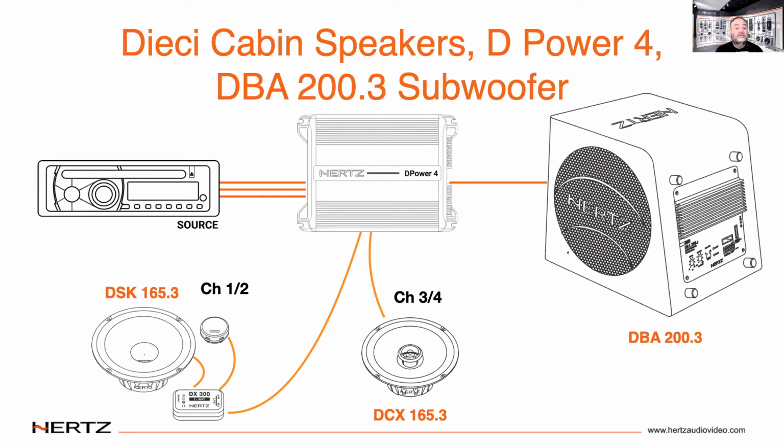Now, also, there's a high-pass crossover filter in the D-Power 4 amplifier. And if you use that, you can attenuate the low bass notes before the cabin speakers try to play them. So that would lower the distortion even more from the cabin speakers and improve the dynamics of the entire system. And it has some other benefits, which we'll explain more in a moment.